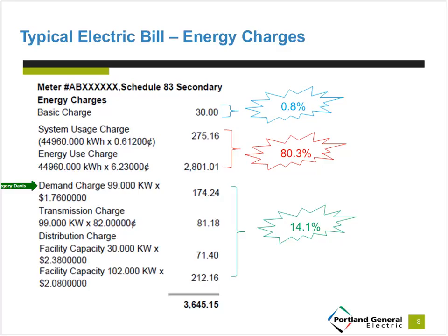I'm sure many of you know that when you turn on a light bulb, the most energy that you're using for the light bulb is right when you turn it on, and then it just uses a steady state amount of energy. Same with equipment, especially large motors and things like that. So we will charge you if you are using some large piece of equipment and turning it on and drawing a lot of electricity in a specific amount of time. That's what the demand charges are.